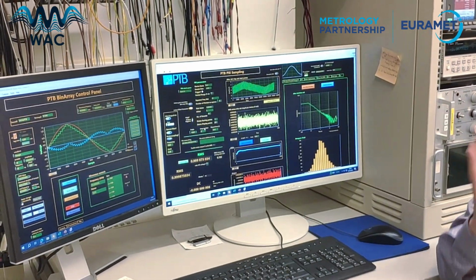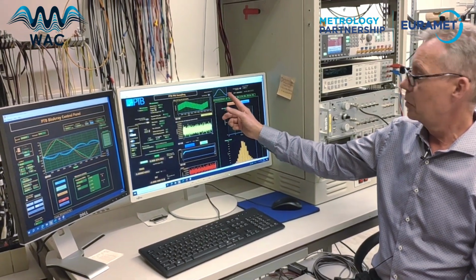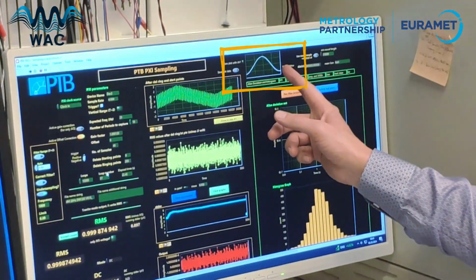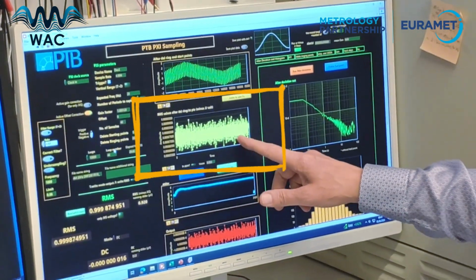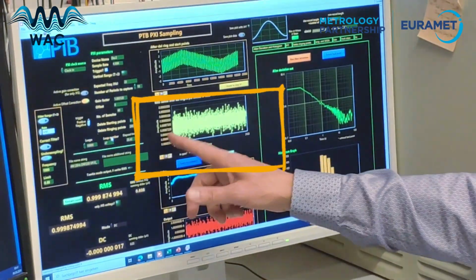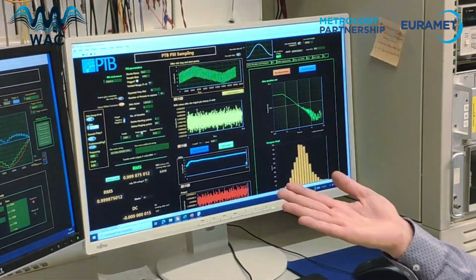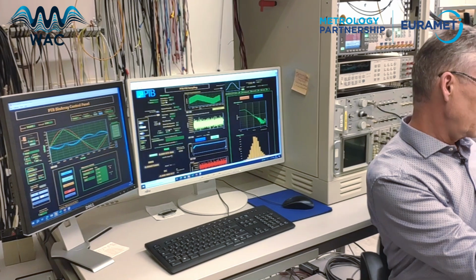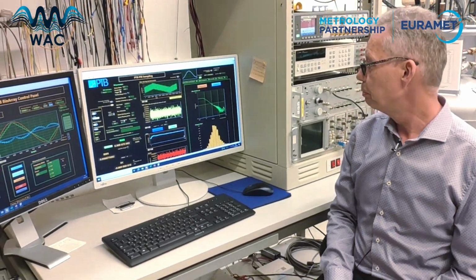Because everything is properly timed and triggered, I can recombine it to a sine wave measurement. As before, this was a differential measurement, and now I'm going to subsampling, and there's no change in the value, which shouldn't appear because we are measuring the same generator at the same frequency and the same voltage output, 1 volt.